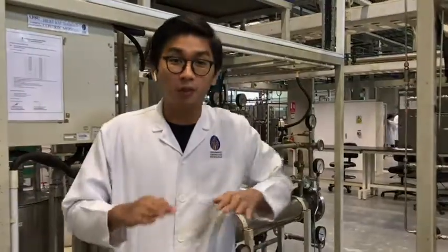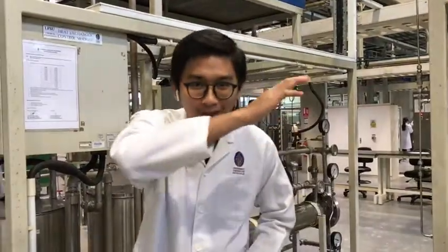For your information, the P controller will reduce the offset, but it won't reach the set point at all. Next, for PI, it will eliminate the offset, so there will be no offset, but it will produce oscillation. And for PID, it will eliminate the offset, and it will reduce the oscillation. So, as a result, PID is the best controller compared to P and PI, because we can get an accurate result and reach the set point faster.